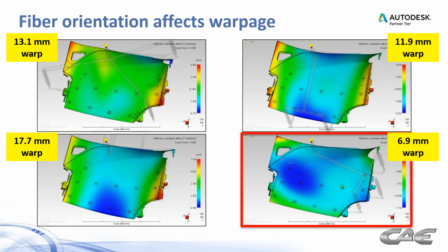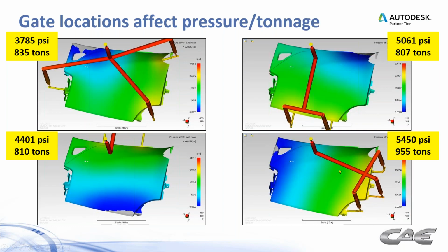And so unfortunately, there are many times going to be cases where even though you do everything right with gating and so forth and cooling, you're still going to end up with some warpage. We also have to pay attention to the processing end of things, right? The one in the lower right was best for warpage, but the worst for processing. But as long as it's still within our processing window, then obviously we can still manage that.